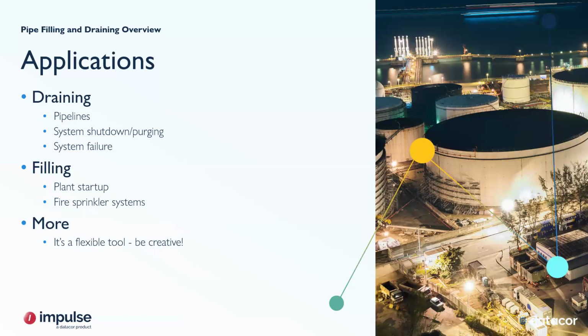But there are a lot of other uses for this feature. Maybe your process fluid is the vapor and you want to model water hammer occurring from some fluid entering your pipes. Maybe air entering and exiting a system from a vacuum breaker valve as a result of water hammer. Or some part of your system uses gas for surge mitigation. We do have a gas accumulator at junction, but this is another option that may have advantages for certain models if you want to model it with friction and the height effect.